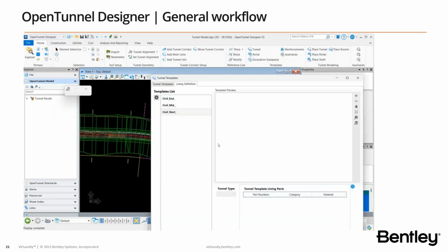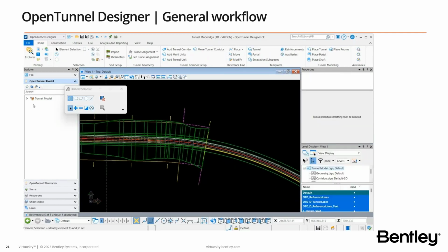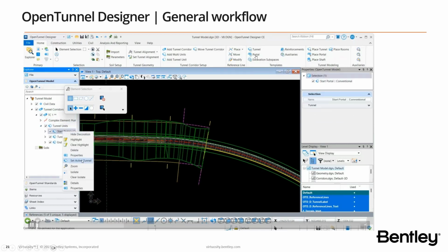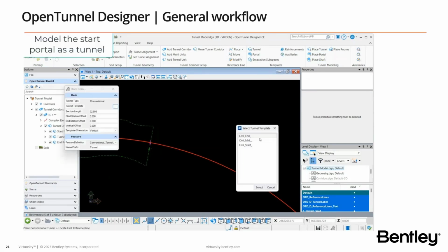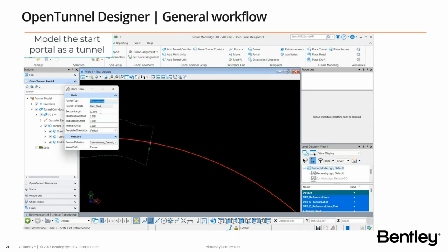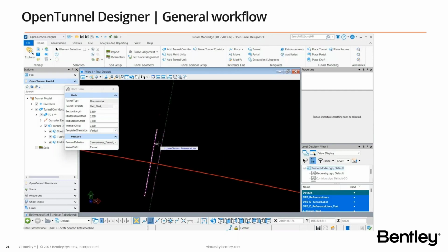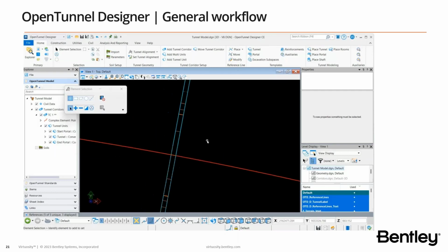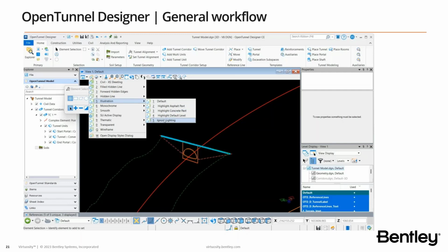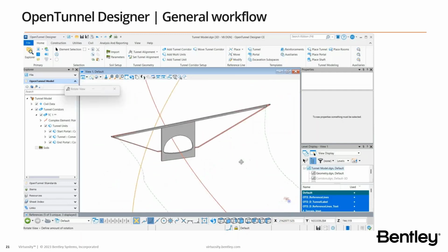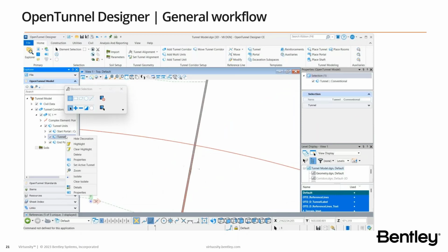In here, I have tried to model, and you'll see the result also. We have a dedicated command for portals, so we have the portal element, but I have tried to do maybe something that is of more interest. I've created a portal as a small section of the tunnel, and for that portal, I also created a pile wall where I have used the rockbolts command to create those piles. So you can see there that we have on top the cap beam, we have the wall defining the entrance into the tunnel, and later on we will see how we are adding the reinforcement for that object.